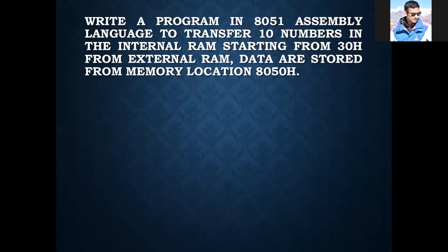Firstly, we will write a program in 8051 assembly language to transfer 10 numbers to the internal RAM starting from 30H from external RAM. Data are stored from memory location 8050H.